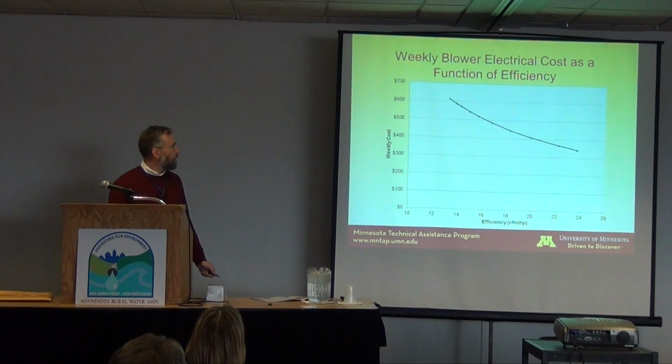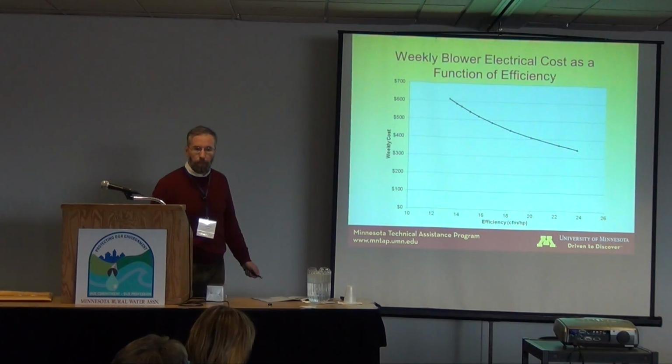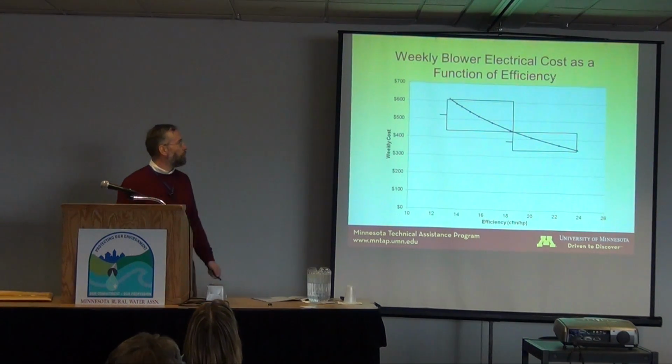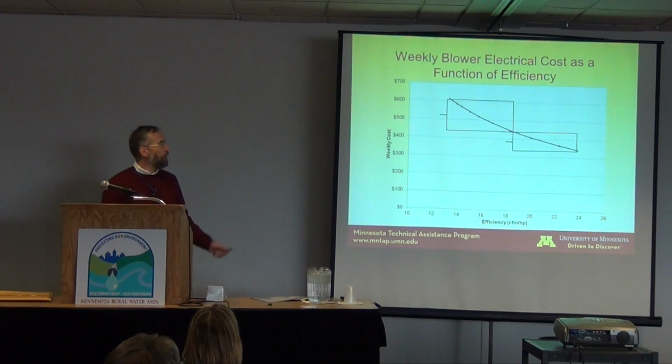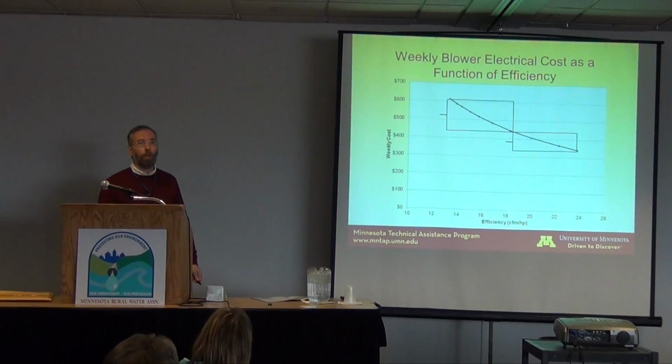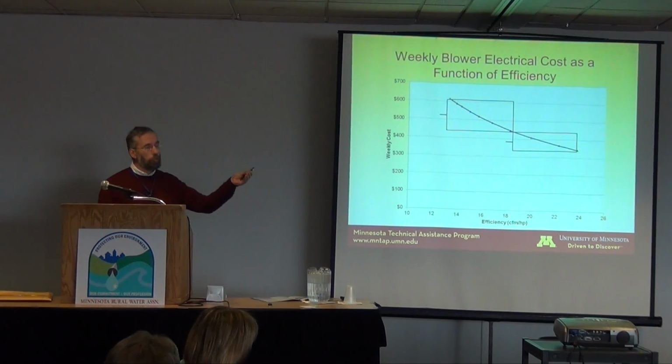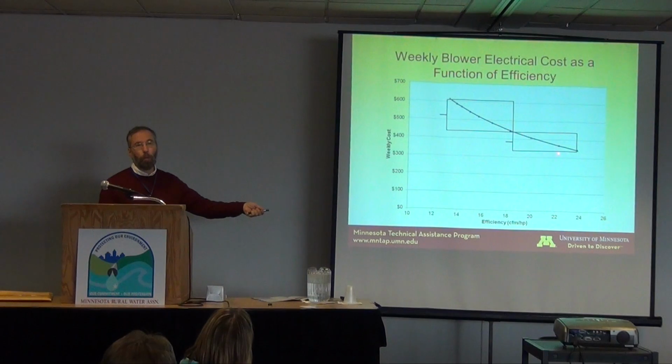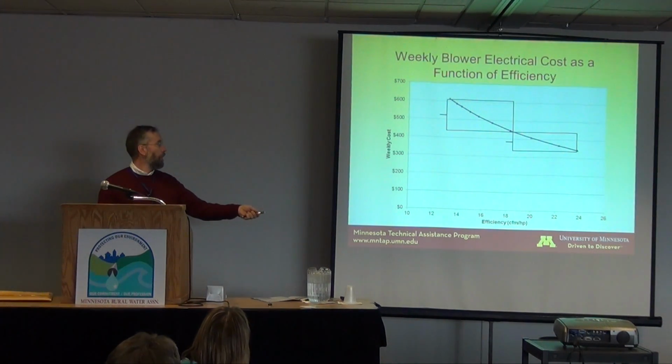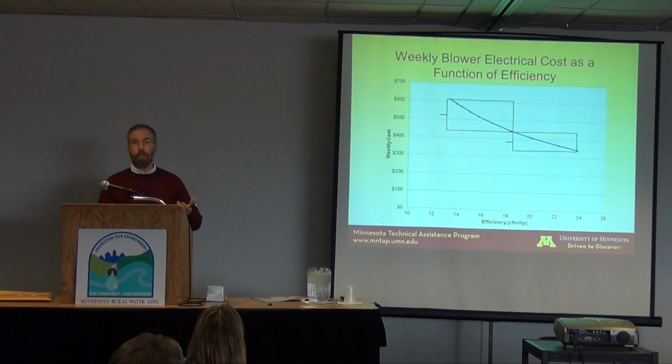and let's see. I guess let's go next one more time. I had intended to take that one slide out, but this puts that same curve on the format of what does it cost to produce 1,000 CFM. So at this end of the curve, that blower is able to produce a lot more CFM, but per 1,000 CFM, the cost here is about $350. At the bottom of the curve, it's almost twice as expensive to get 1,000 CFM. The capacity has definitely changed, so there's definitely differences.